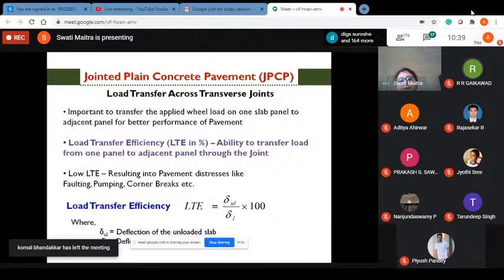So you have to find which is the most critical lane, and that lane will be the design lane. Now for design traffic, the legal axle load limits in India are, for single axle 10.2 ton, tandem axle 19 ton, and tridem axle 24 ton. But recently the legal limits have been increased. But this is as per the IRC 58/2015 code.